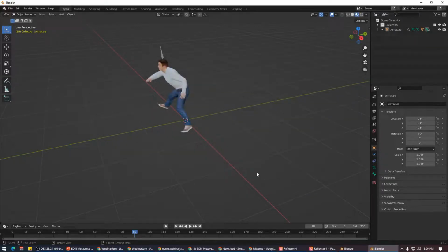So importing my FBX and playing it in Blender, not necessarily, because the FBX is an Autodesk format. It's not pure Maya. So FBX could be in 3ds Max. The only thing is, right now, I don't have the latest 3ds Max which supports GLB, because the latest 3ds Max 2023, as well as I believe Maya 2023, supports export to the GLB format, which EON uses. And Blender has that already. And yes, Blender will convert the format with animation to be used in EON-XR.